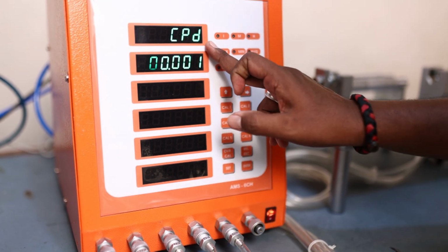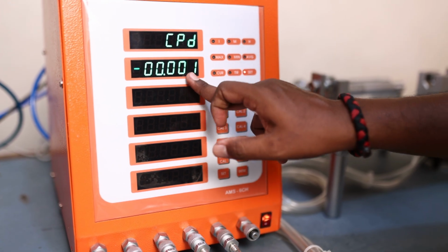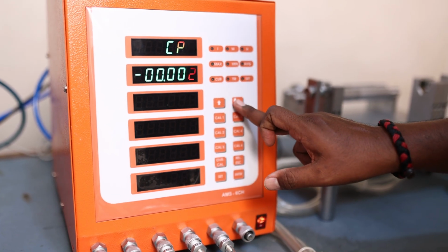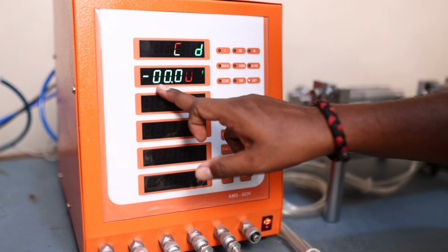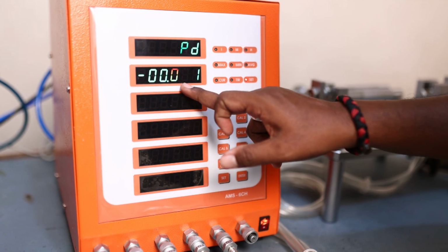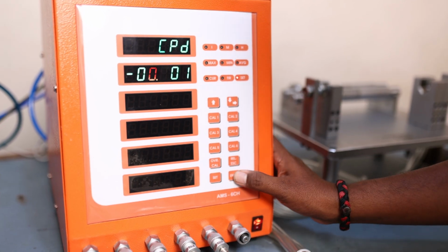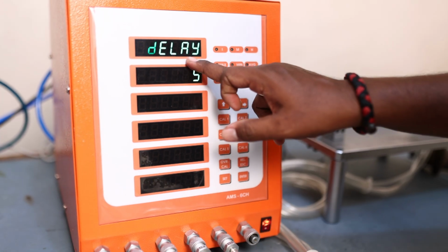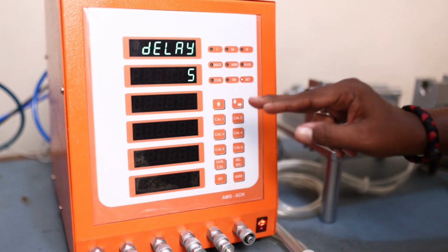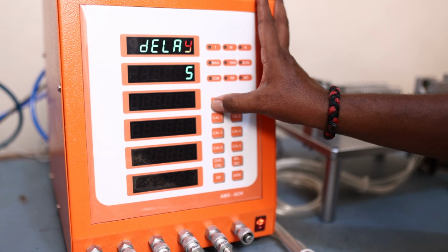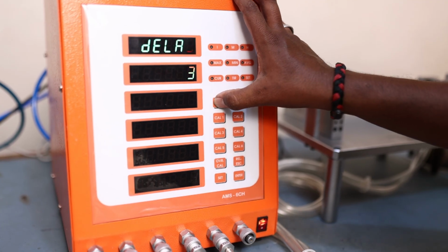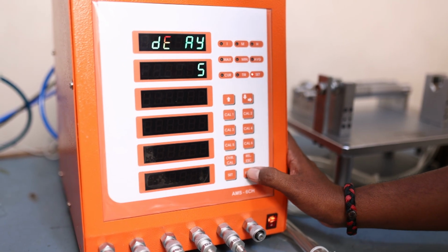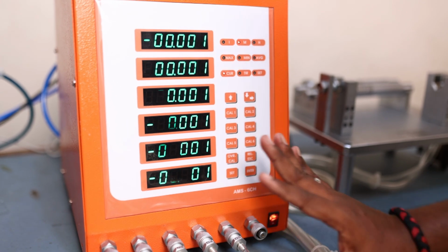And this is the password for program number 2, function number 2, which you are going to set. You can change it if you want. Now I am entering -00.001 and pressing the enter key. Now this delay option is coming. This is for sending the data output through RS-232. You can select the delay time. I have set 5 millisecond right now and I am pressing the enter key. Now the program is set.